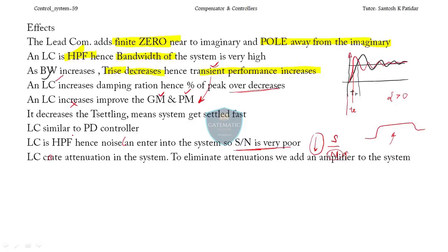What we were doing there was putting one amplifier in series, and the amplification of that amplifier is 1/α. The 1/α multiplies with whatever you got there, and with α in the numerator divided by α in the denominator, you get the standard transfer function (1 + sτ) / (1 + αsτ).